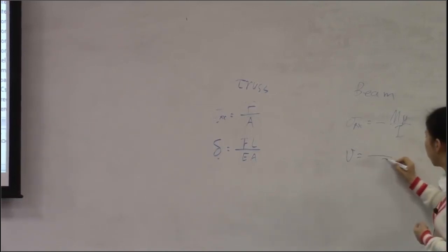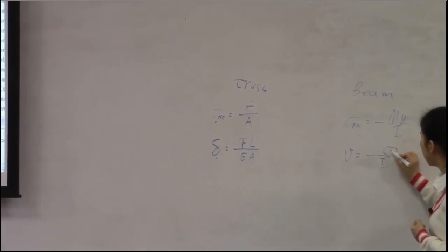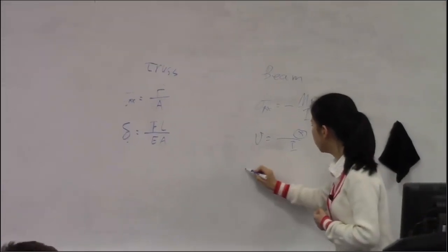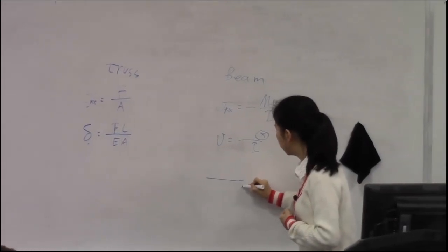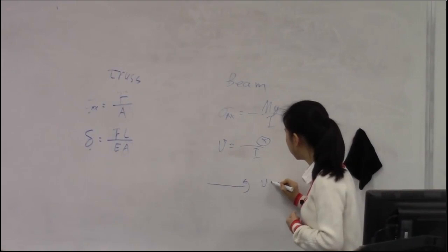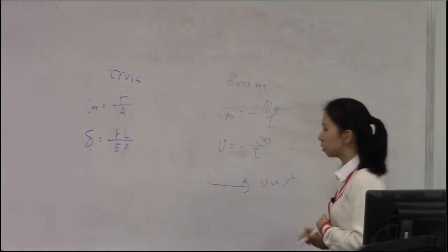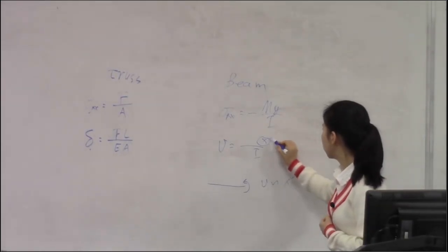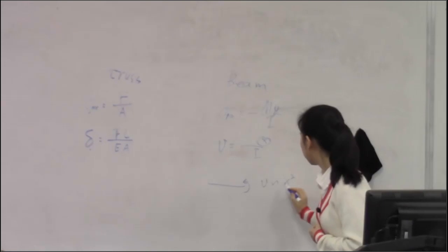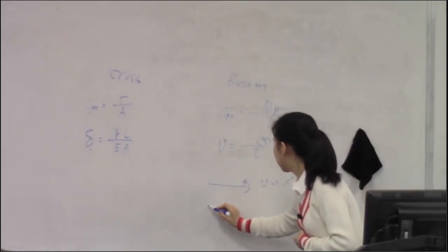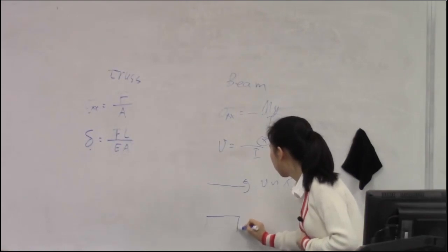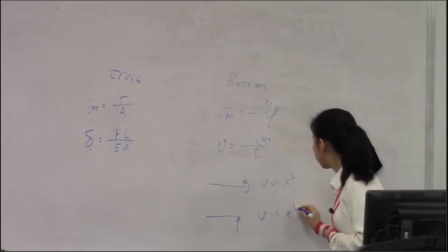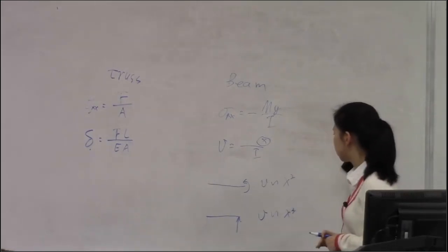So it should have a moment of inertia here, and here you have a function of x. If the loading condition is a bending moment, the deflection should be a function of x, quadratic here. And if it's a concentrated force, this deflection should be a cubic function of x.